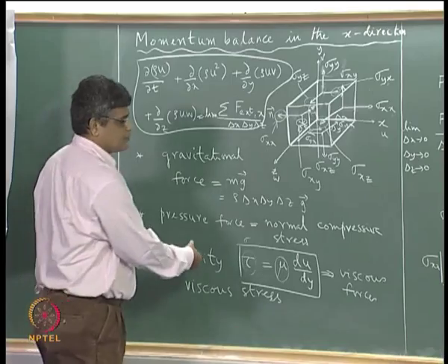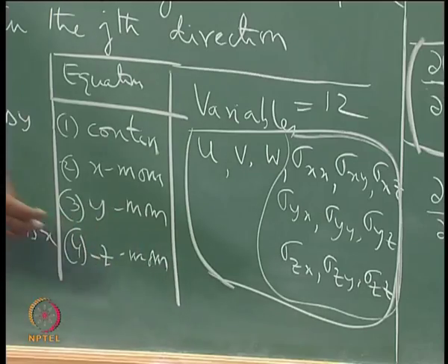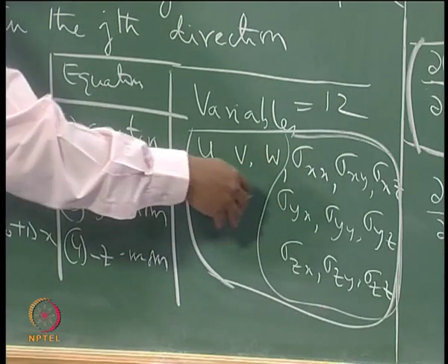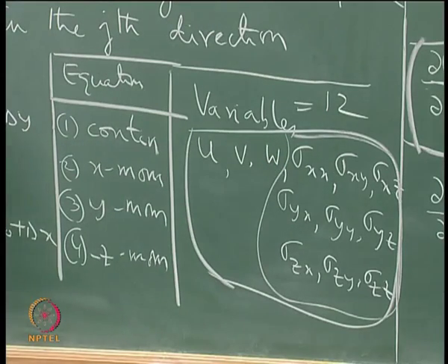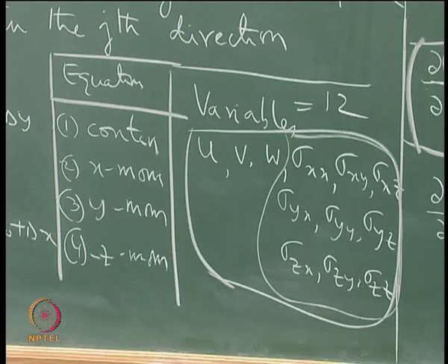Okay, so these kinds of relations are needed to describe each of these stresses, so that these stresses can be replaced by equivalent velocity gradients and viscosities and all that. If we have that, then all the stresses would disappear and we will have a much smaller number of variables. So we are looking for a constitutive expression for what the stresses are.